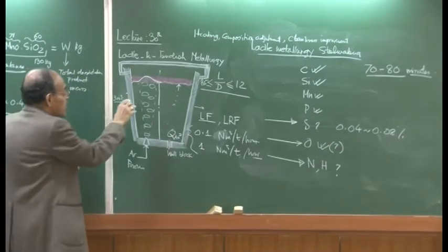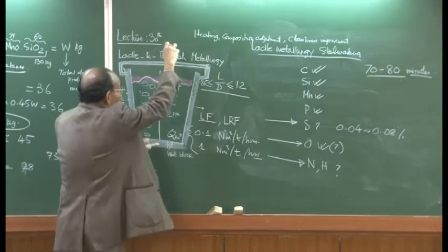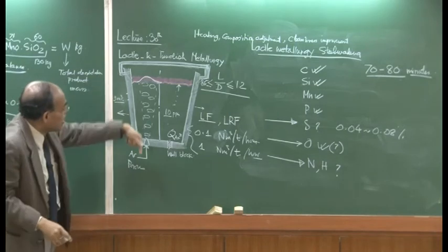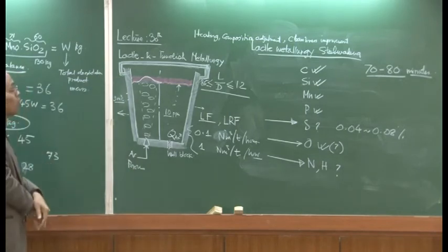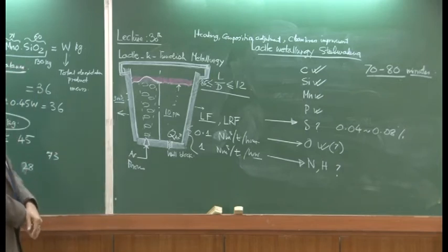So, because the steel is killed, because it contains only 10 ppm oxygen, there is a large difference in oxygen gradient. So, from the atmosphere there is a great tendency for oxygen to dissolve into the molten metal, and that we need to prevent at any cost if we want to ensure that reoxidation does not take place. Reoxidation, as we will see, will